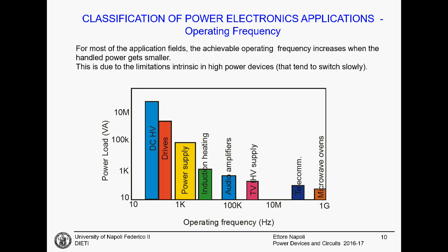But obviously there is no other kind of comparison, because digital circuits can be so fast because they use the trick that they need just to process the information. And reducing the energy that is stored in a single bit of information, reducing the supply voltage, making the single bit MOSFET very small, this can reduce the amount of energy, and this means that we can switch at higher frequencies. This is the physics that is behind the scaling theory.